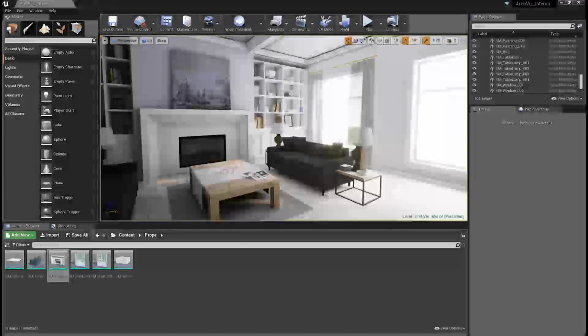Now there are a few settings that we can tweak in order to try to get a better result, and the first one is the near clip plane. If you know much about cameras in 3D, you know that they have what's called a view frustum, and that has a far plane and a near plane where things are clipped out. They aren't rendered. The near clip plane is in the front part of the camera, the very closest part to the camera lens.